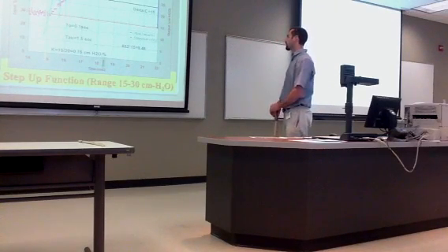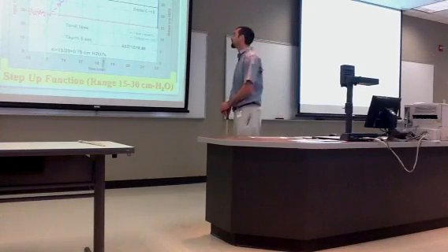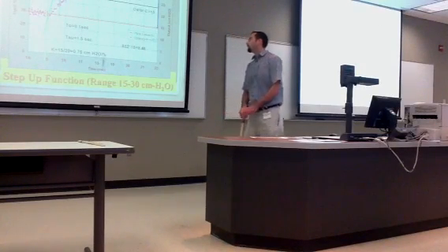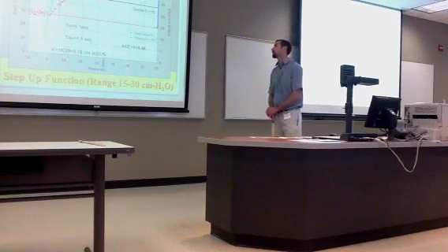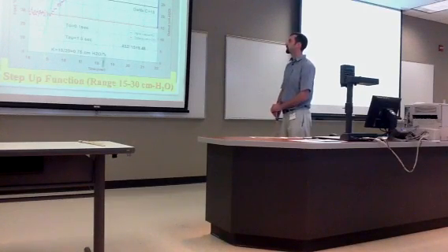This is the step-up function from range 15 to 30 centimeters of H2O. Our delta M equal to 20, delta C equal to 15. Our T naught was 0.1 second, and tau was 1.5 seconds, and K ended up being 0.75 centimeters of H2O per percent.